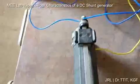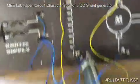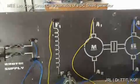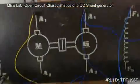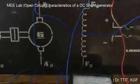We have a 140 ohms rheostat that is connected to the field winding of the motor, and a 50 ohms rheostat that is connected to the armature of the motor. What we are going to do now is bring the motor to rated speed so that the armature of the generator will rotate. And slowly allow current to flow through the field winding, and we are going to see how the voltage is going to build up.